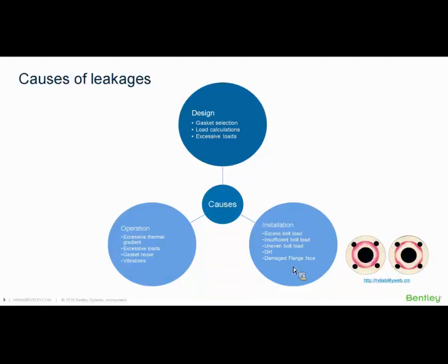On the left picture, you can see a pressure film which captures the pressure onto the gasket. In the right one, over here in the pink color, this is the pressure on the gasket. The difference between these two is that one was tightened with washers on the studs and the other was without. So you can see that you already have leakage possibilities in the areas where there is lower pressure, and that could cause a flange leakage.